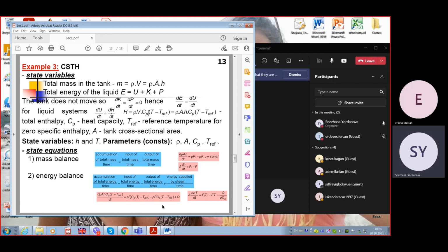So the disbalance between entering heat and leaving heat and additional heat. We have here two variables that change with time in this derivative, h and T, temperature, so level and temperature, the two outputs of our plant depend on time.